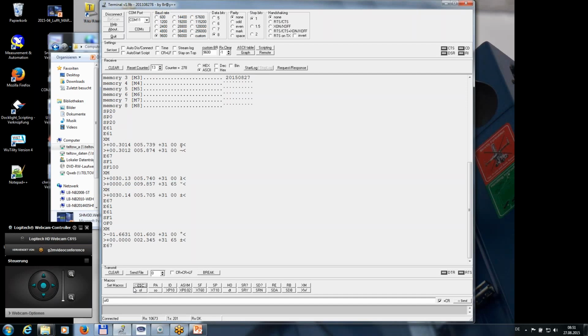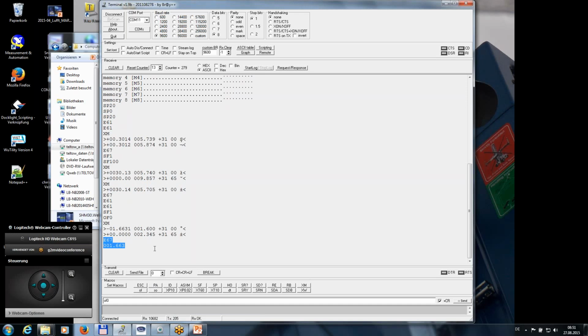And this value which is measured here is always subtracted from the offset, because finally we want to have snow depths. And with the snow depth, it's a positive value, so we want to see something that is growing from the ground. So we level the ground to 0 by doing an offset measurement. An offset measurement can be done by the command SO. If we start it, it's done here, and the output is O 1663.